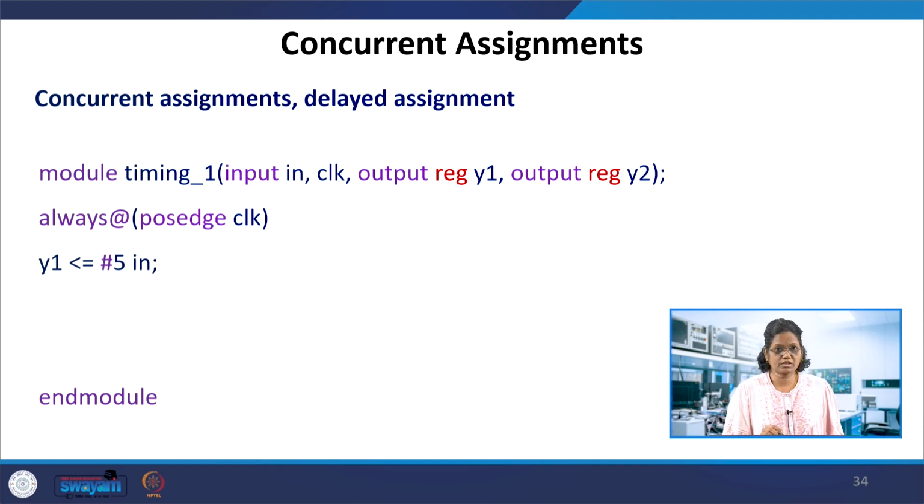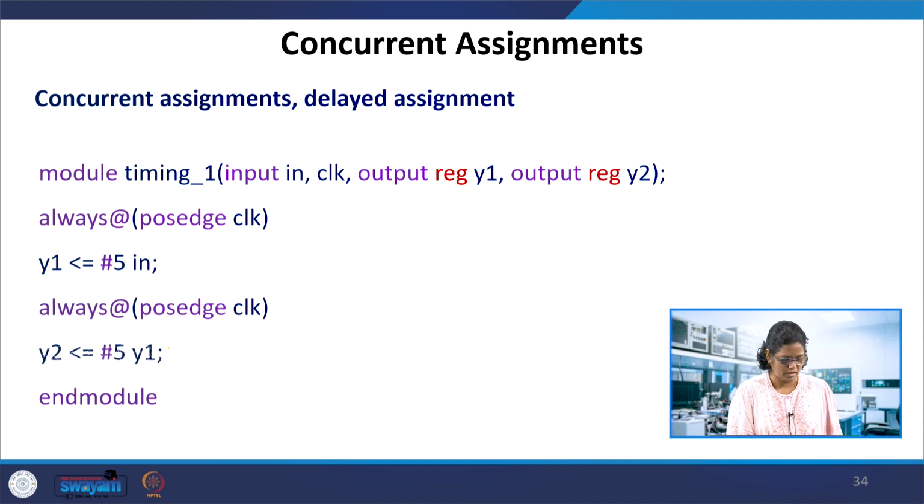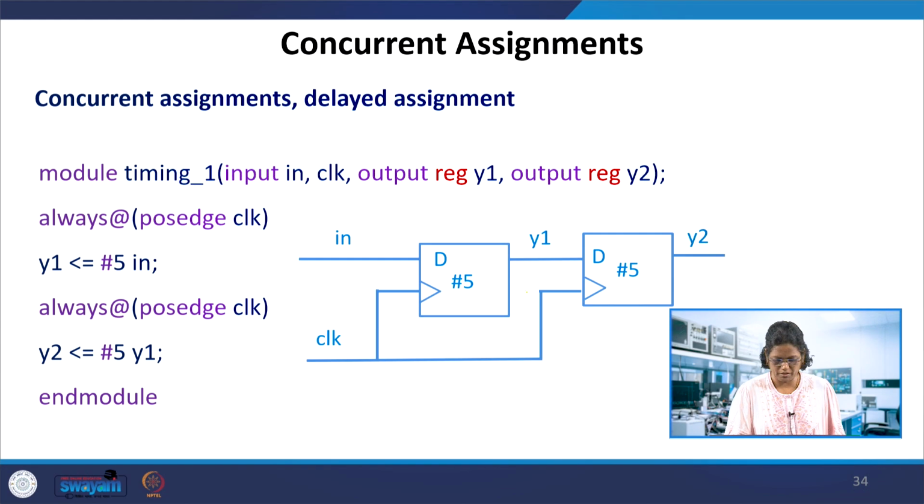So only the glitches would be passed or not. That is the only case which has the problem. If there are closer glitches, this case would not pass. So in the concurrent assignment with non-blocking, this would also form the similar thing, because it would closely watch the input change here. As we have seen in the intra-assignment delay with non-blocking assignment, it's equivalent to the transport delay if you use it in one always block.